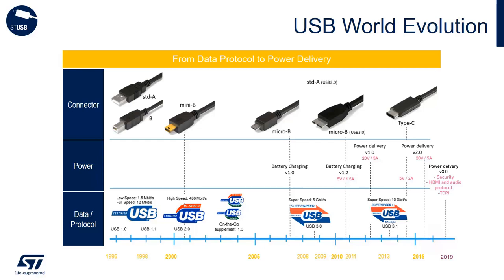Recently, we have seen some press releases about the USB Extended Power Range optional layer, which will support 48 volts at 5 amp, equal to 240 watts of power. That extension is mainly being driven to address PC applications, where 100 watts was not quite enough to quickly charge a laptop battery. It's still pretty early in the EPR development, but ST has a presence in the USB working group, and we will be ready to provide controller and power solutions once that market develops.